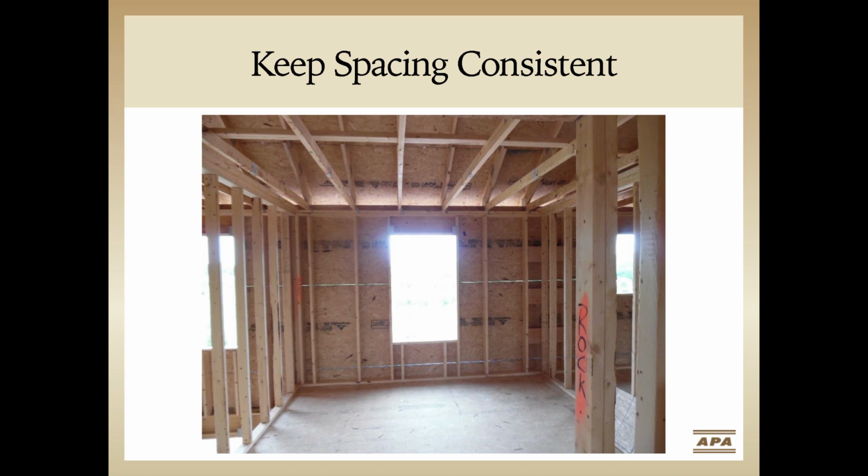And just one further note on this wall, if these panels happen to be brace wall panels and acting to satisfy the IRC wall bracing requirements, then they would likely need to be blocked along the panel edges. And it's very possible that the blocking, if required, just hadn't been installed yet at the time of this photograph.